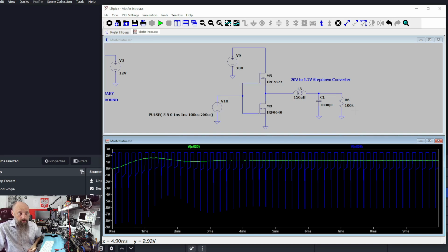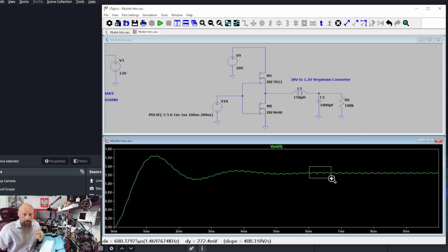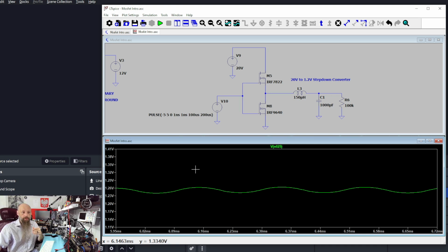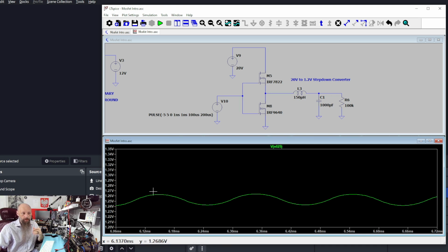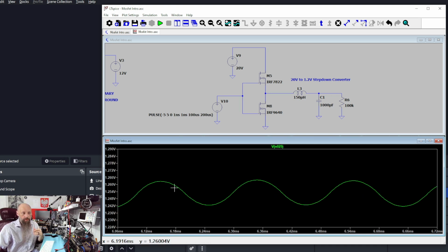But depending on the circuit, typically there is no resistor outside of the coil. The coil goes directly to the output. There's obviously going to be some capacitance on the output, because otherwise we would have a lot of fluctuation. But if you check on the oscilloscope, there's always going to be some fluctuation. As you can see here, you're always going to see this on the output.